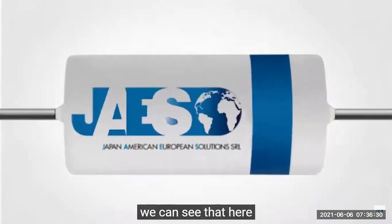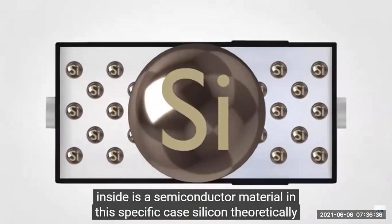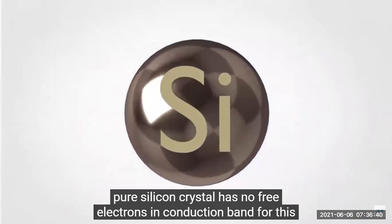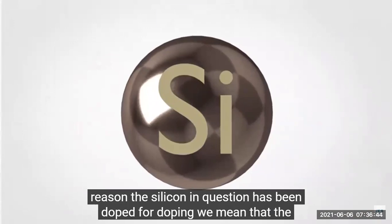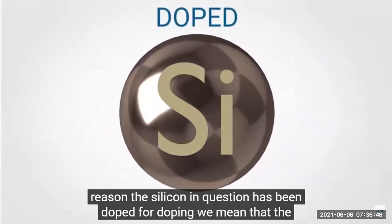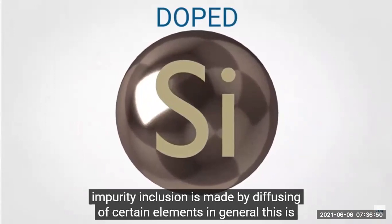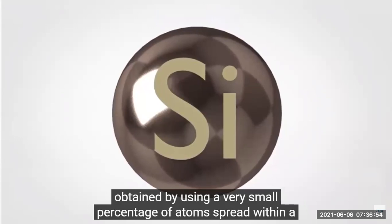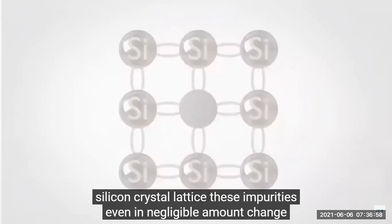We can see that here inside is a semiconductor material. In this specific case, silicon. Theoretically, pure silicon crystal has no free electrons in conduction band. For this reason, the silicon in question has been doped. By doping, we mean that the impurity inclusion is made by diffusing certain elements. In general, this is obtained by using a very small percentage of atoms spread within a silicon crystal lattice.